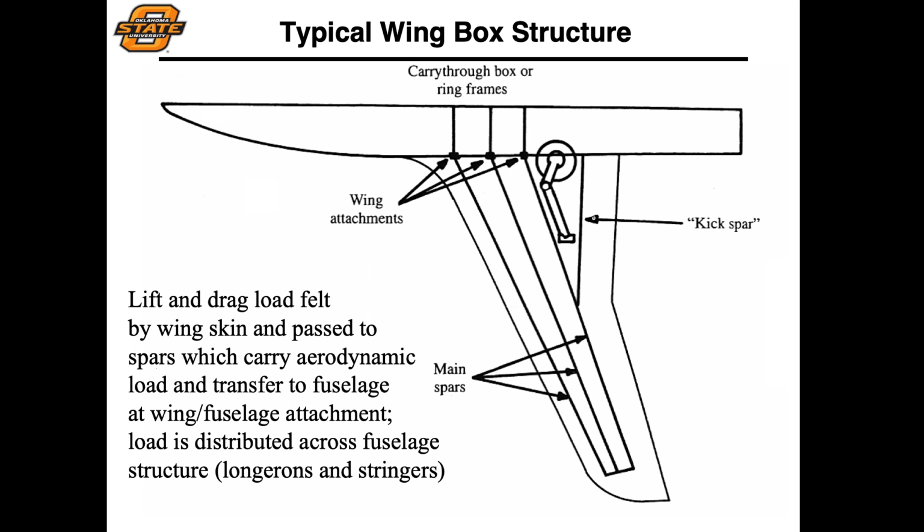Mainly at this point, we really have to think about things such as consideration. When you're designing elements such as spars within your aircraft, where's that gear going to go if you're going to have a stowed gear? Think about where everything has to fit in relation to those structural elements. Do you have enough volume to put everything in there? Do you have room for your gear? Do you have room for your fuel tanks if you have a wet wing?